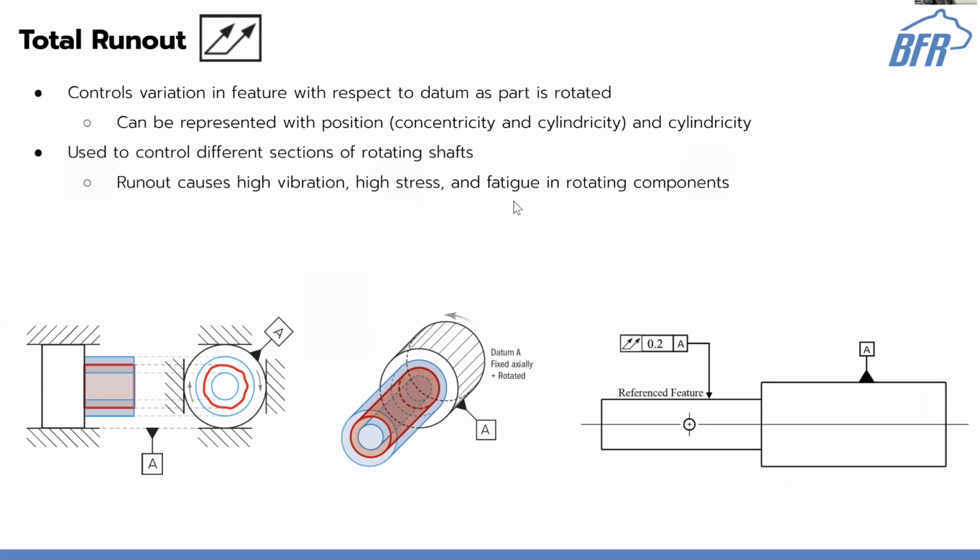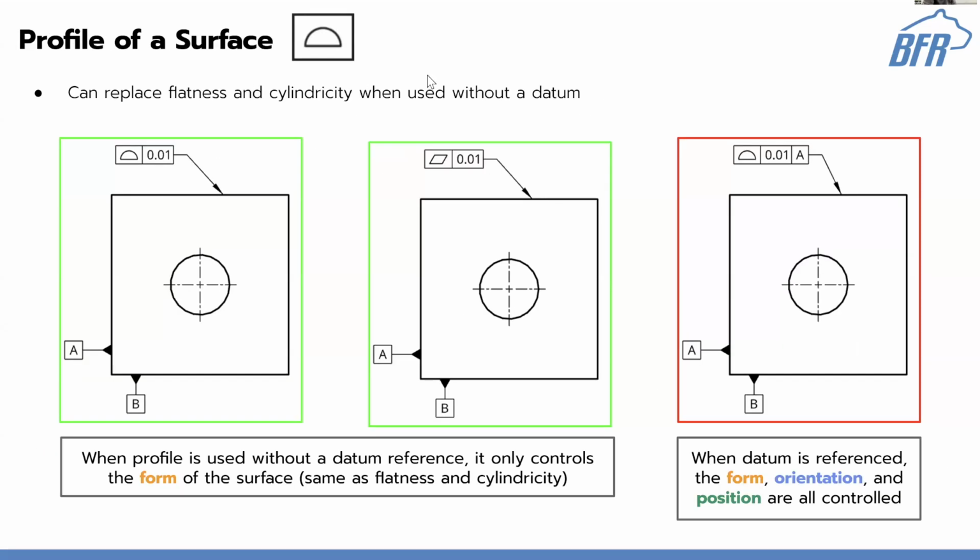So yeah, you'll actually see this on some of the drawings, I'll pull it up later. A pretty common thing is you'll say there's an overall total profile tolerance of a pretty loose number, and you just throw that in there.